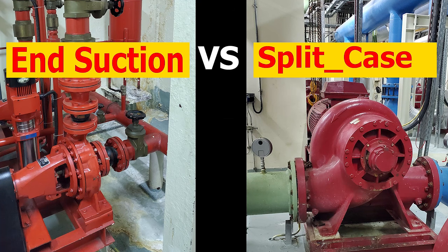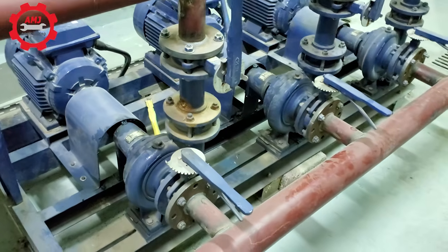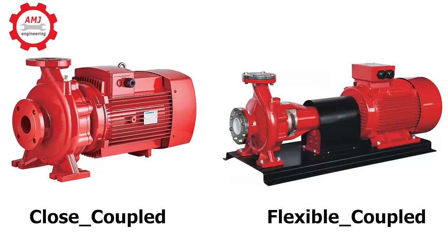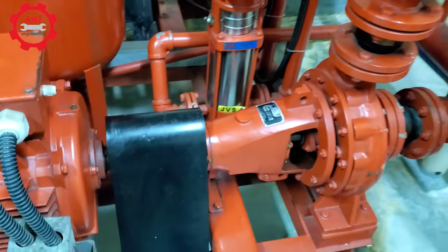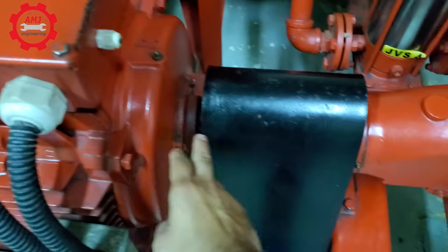Hi gents! In today's video, I'll go through 2 of the most used pumps in HVAC industry: end suction pumps and split case pumps. End suction pumps are single suction, that means the fluid enters the impeller from one side only. End suction pumps can either be closed or flexible coupled. A flexible coupled end suction pump, as in our case here, has the impeller and the motor shaft separated by a flexible coupling.